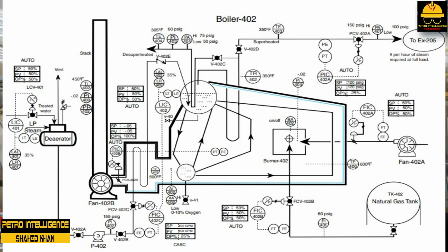As the temperature of the water inside the generating and riser tubes increases, the density of the water decreases and initial circulation is established. Bubbles begin to form and rise in the water, increasing circulation and pressure. Each time the water passes through the tubes, it picks up more heat energy. When the pressure increases to slightly above the system pressure set point, steam will flow to the header.